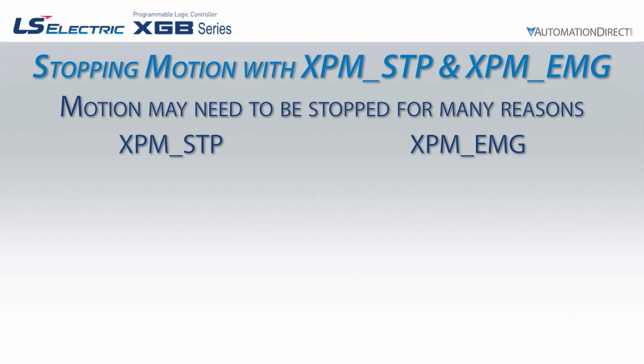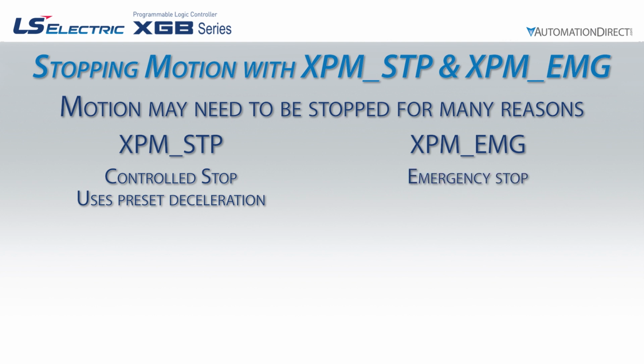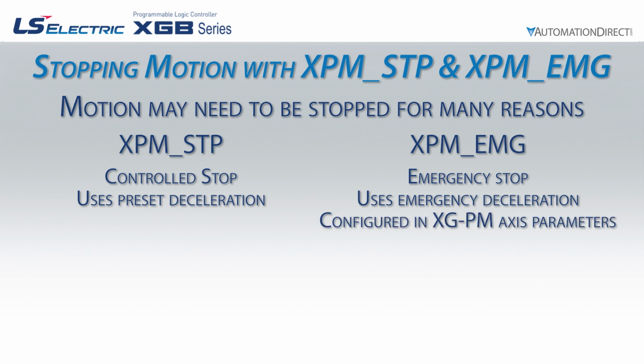The XPM_STP, or decelerating stop, function block allows the user to have a controlled stop based on a preset deceleration time. The XPM_EMG function block is an emergency stop that stops the motion command based on the decel time for emergency stop parameter in the XGPM software. This parameter defaults to 0 milliseconds.